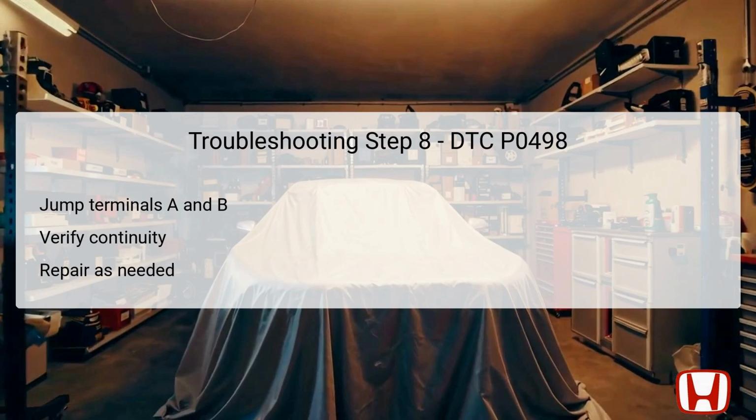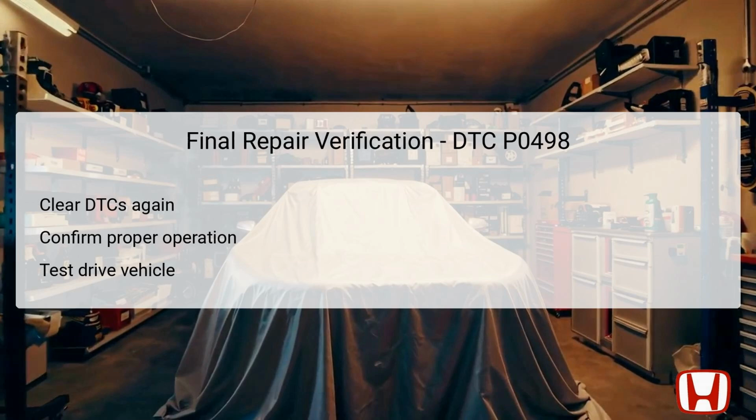If it is confirmed intact, it may necessitate updating the PCM software if it's not current, or substituting it with a known good unit to further diagnose the P0498 issue. If the DTC clears post-update or substitution, the troubleshooting process concludes successfully. However, if there is no continuity, it suggests that an open exists in the wiring that must be repaired to resolve the P0498 fault. Upon completing the troubleshooting and potential repairs for DTC P0498, the last step involves verifying that